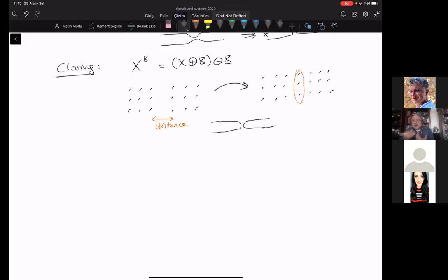Of course, they are not connected, they are disconnected, but they are too near to one another. And according to some high frequency signals or high voltages, there may be an arc from here to here. There may be a capacitive effect between the two, or they may be considered with a high resistance, but still with a connection, okay, at some frequencies. So it's a dangerous thing.